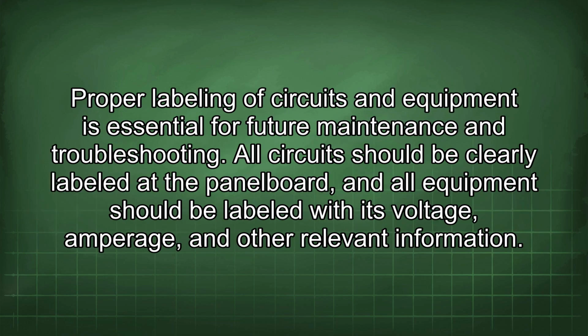Proper labeling of circuits and equipment is essential for future maintenance and troubleshooting. All circuits should be clearly labeled at the panel board, and all equipment should be labeled with its voltage, amperage, and other relevant information.